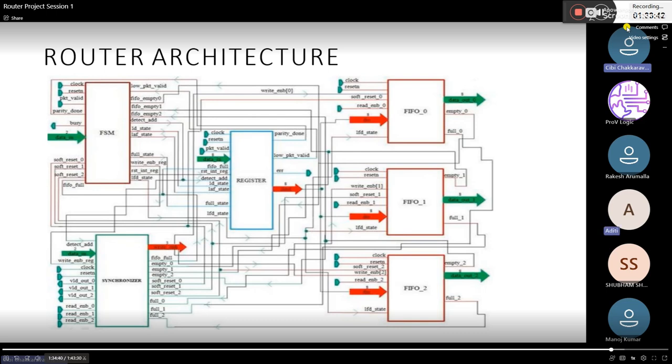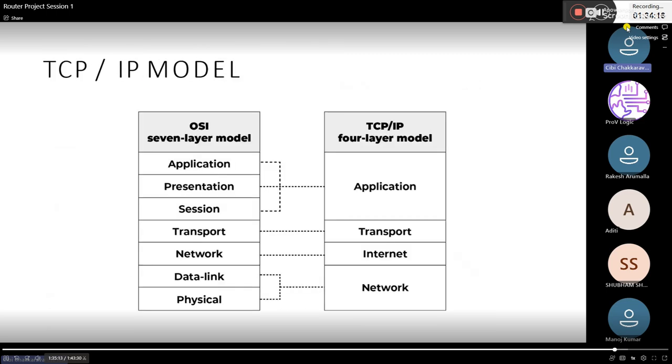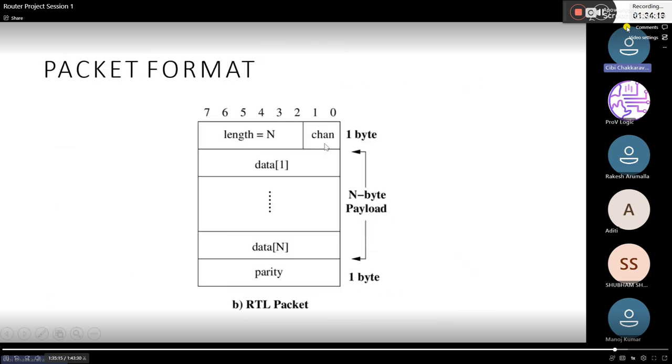I am asking here only three FIFOs are used, but it can be more or less, no? We can add extra FIFOs? Yes, our project is 1x3, but if you have more than 3 destinations, you can add more FIFOs and implement the signals, and you can see what will change based on our knowledge. Our address should be incremented.